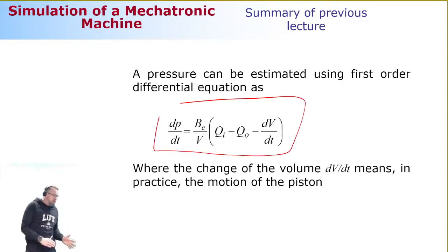And by the way, it's extremely important, before you do this, while you do the discretization, that you also describe what the positive direction of the flow is. You can do this anywhere you want, but something that is extremely complicated and hard to do is to be consistent. The way you can be consistent is that you have this physical description of what you think is the positive direction. But like I said, you can define the positive direction any way you want, but you need to define which one is incoming, which one is outgoing.